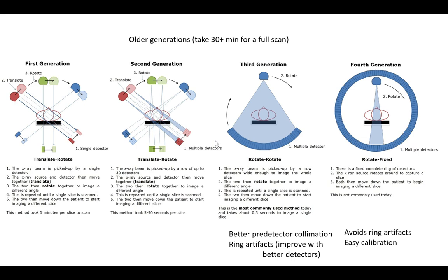One way I can solve that, because if any of them is off slightly in the calibration between them, a certain brighter one is going to rotate around of who is brighter at the time. So miscalibration between your detectors will cause a bright spot that rotates around constantly, because as you move, the bright spot will move in a circle. They're never perfectly calibrated amongst each other, so they just naturally tend to have these type of artifacts, regardless of anything else going on.